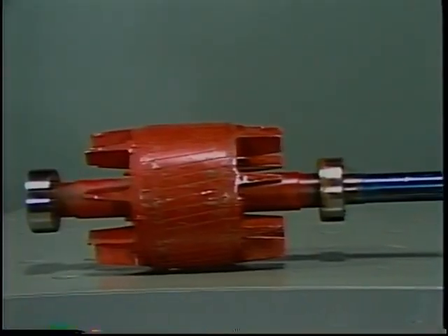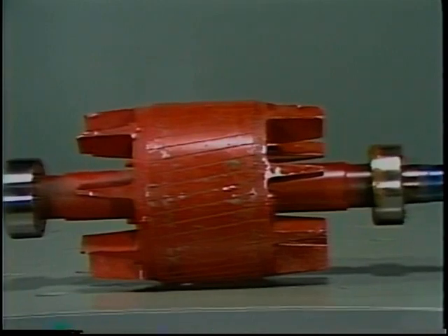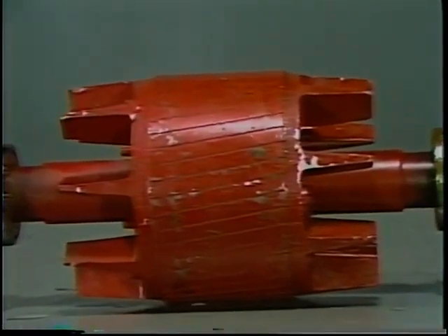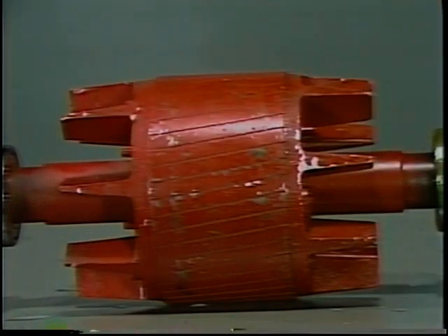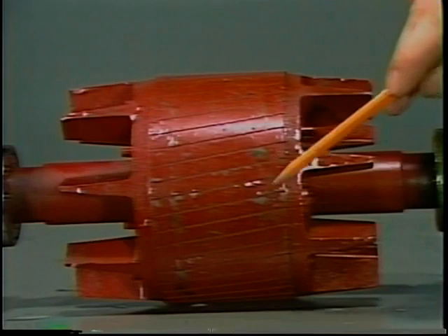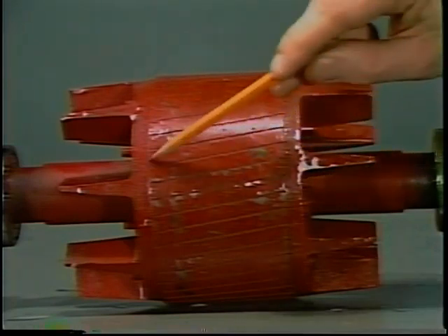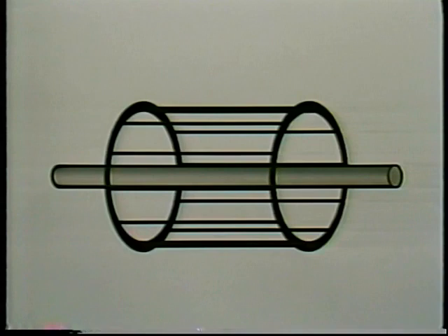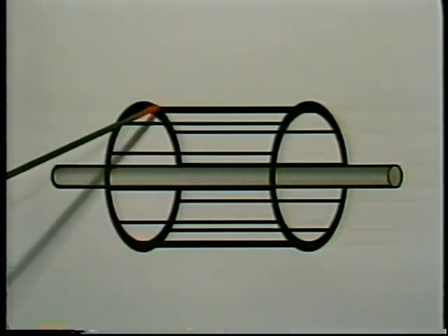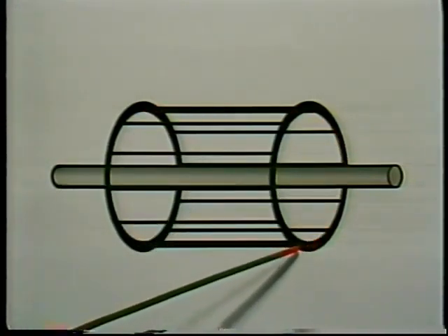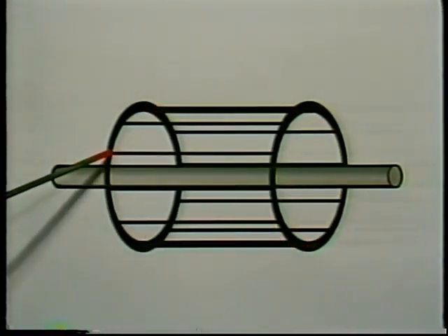Look at the rotor closely. Often, all you'll see is a round core of laminated steel. But notice the aluminum rings on both ends. They are not there just to hold the fan blades, which are usually cast as part of the rings. If you could look inside the iron core, you would see that the rings are connected by solid bars through holes in the core. The bars and the end rings form a conductive cage, often called a squirrel cage. The cage is often cast in place, though sometimes it is assembled from separate copper bars and rings.